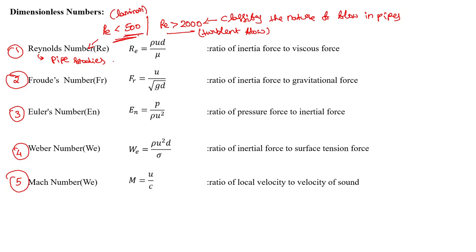For designing such big pipes, we need to construct a smaller model to test the circumferential pressure and tension. In those cases, the dominant number will be the Reynolds number. It means that between the model and prototype, the Reynolds number should be the same, as in pipe studies.